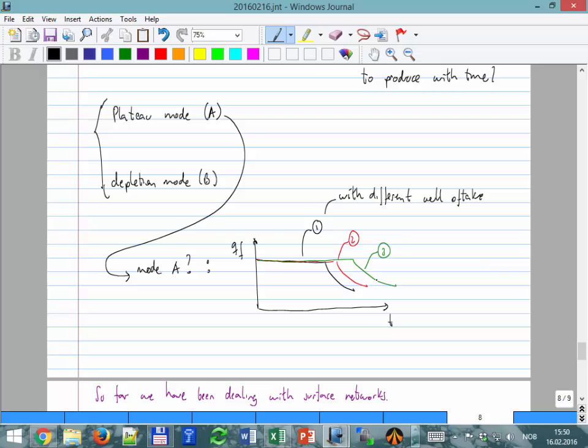And how do we find which one? Now comes the real question. That's very nice, but how do you find this third option? One way people use, and that has been used so far, is that you say that every well has to reach the plateau level at the same time. All the wells have to be open choke at the same moment. At this point, all wells should have open choke.